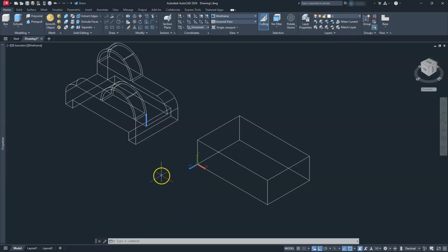Meaning that next I want to create a rectangle. And then I want to type in the starting point of that rectangle, right? So it's 10 over to the right, and then it's 30 tall, right? So my first point here will be at 10, 0, because I want to start it at 10 units to the right. And then I want to type in the size of my rectangle. The X value will be 80, comma, the height of this will be 10. And we'll switch back to the drawing, and I can show you where I got all of these numbers from.